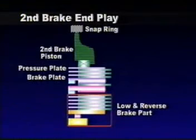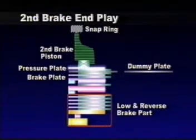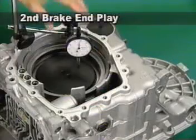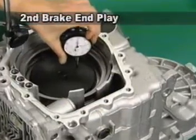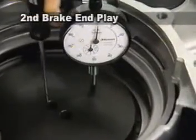Then, change the brake plate that is positioned at the uppermost part of the second brake with special tool dummy plate, and assemble from the bottom low and reverse brake to the top second brake piston and snap ring. Install the dial gauge and measure the end play by moving the dummy plate up and down.